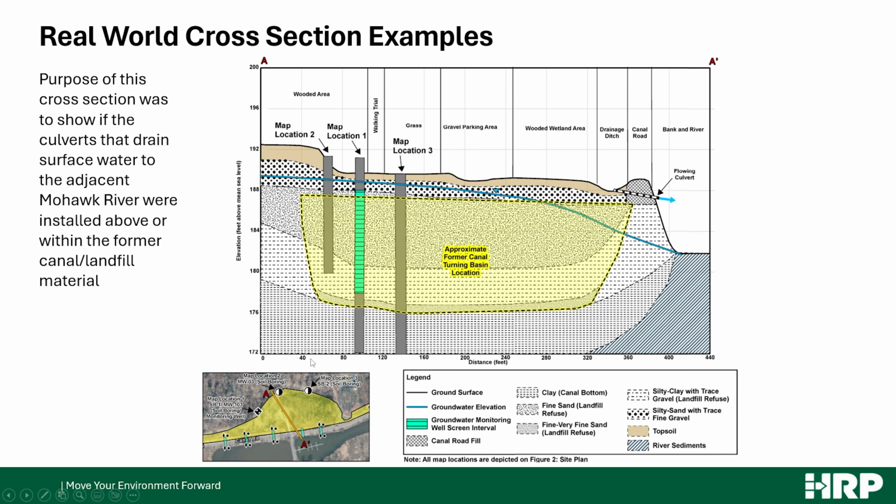This is also an example of how perspective is going to change the order that you're going to display your borings. So from plan view, it goes location number 1, 2, and then 3. But in your line of section, location number 2 is your closest boring to the beginning of your topographic profile. So when you're looking at it from the side view, you're going to have sample location 2 first, and then sample location 1, and then sample location 3. And that's why it appears in that order on this line of section.